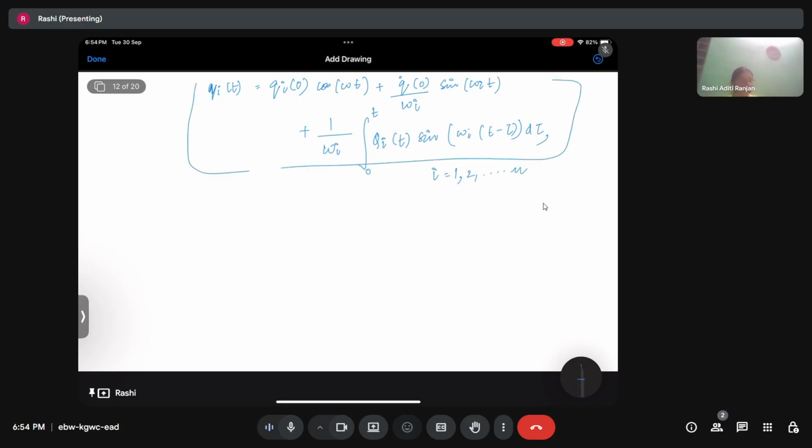So now we know what we have to do. X1 and x2 we have, but we need to find the constants which are multiplied with them. Second, we have to find q1 and q2, and then we can calculate the solution. Anyways, this is easy because the third term in our case is going to be equal to 0, as it is the case of free vibration. So by orthogonality,